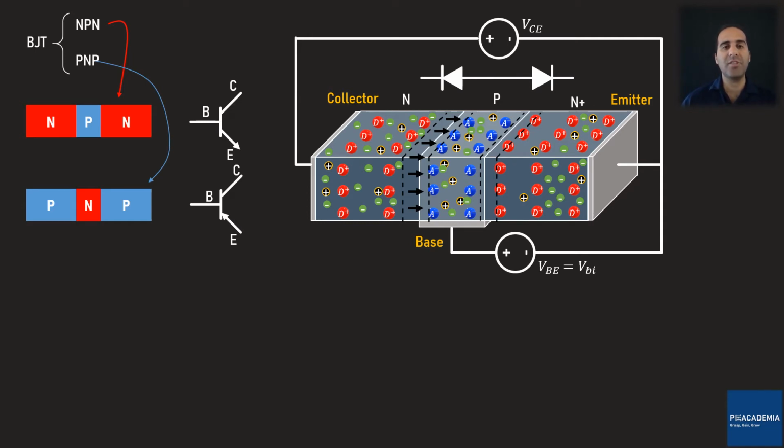This electric field sucks in most of the electrons and injects them into the collector, and from there they will leave the device through the ohmic contact. A minority of electrons emitted from the emitter is absorbed by the base and leaves the device. I think you now understand the reason for the names collector and emitter. Emitter emits electrons, collector collects those electrons going to the base region.